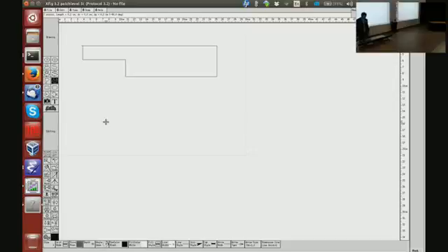The flow will come from the left-hand side. It will come out of the right-hand side. The top and the bottom patch will be zero. Okay? So what I expect to have is a recirculation region somewhere around here with the flow going around.